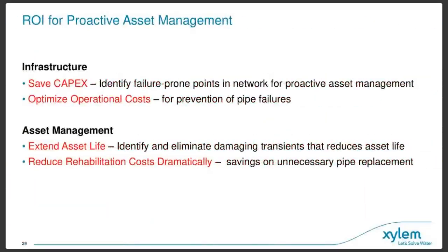So just to summarize with the proactive side, it's helpful for predictive assessment using pressure transients, consumption data, and the GIS information within the network to be able to understand areas in the network where there may be high risk and target leakage activities or repair and replacement, but also being able to mitigate and root cause those problems by being able to localize and identify potential customers or operations that are causing issues.